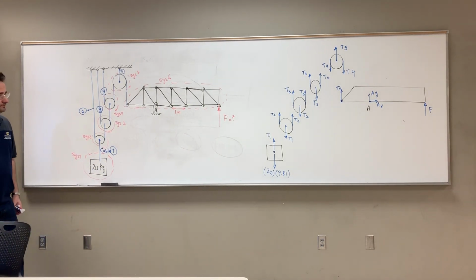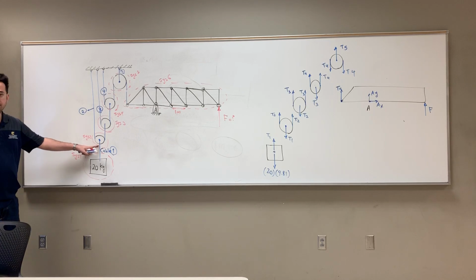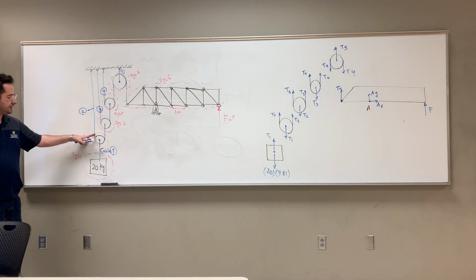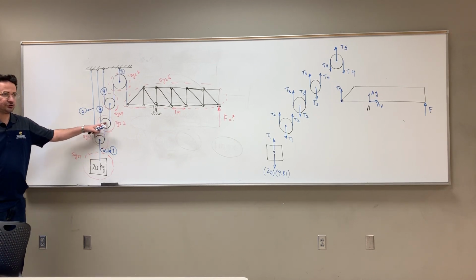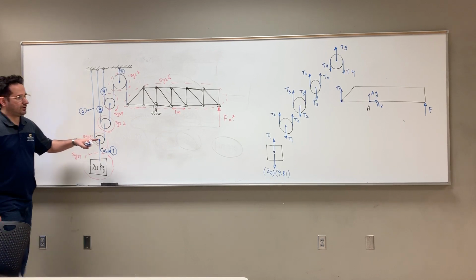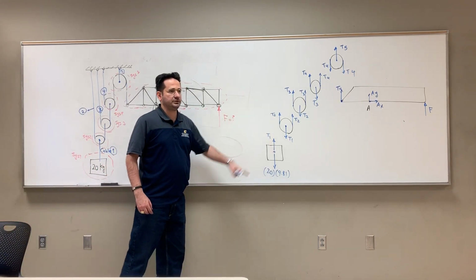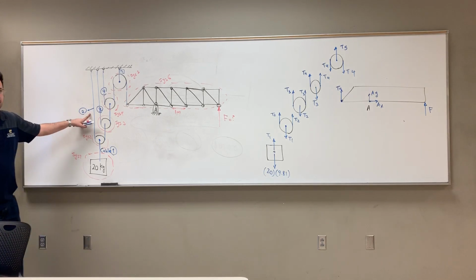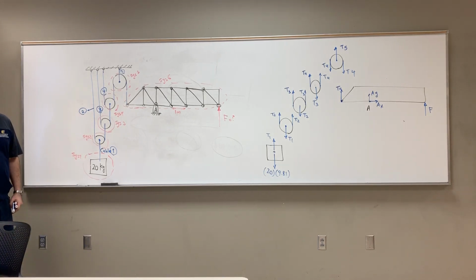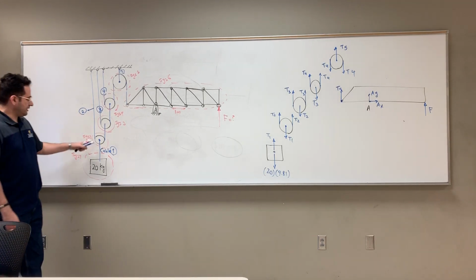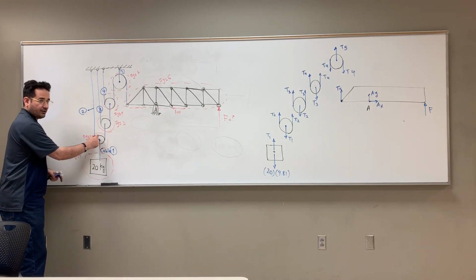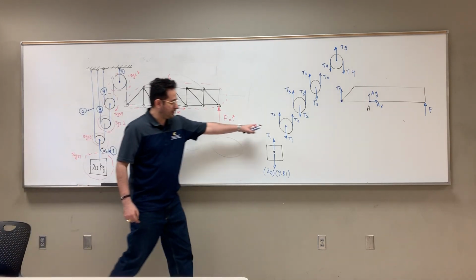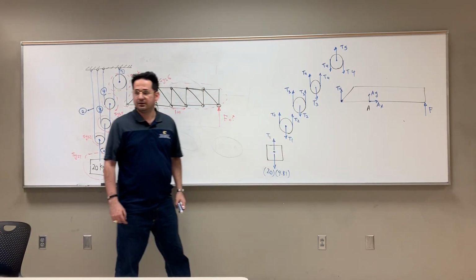As you can see, for system 2, all I did, I walked around it and I cut this cable, and this cable. But look, these two cables are just one cable. So you have one unknown parameter. Let's call it T2 because this is cable number 2. So I say T sub 2. But this force, you see this cable is connected to the center of the pulley. So the force at the center is just T1 coming down.